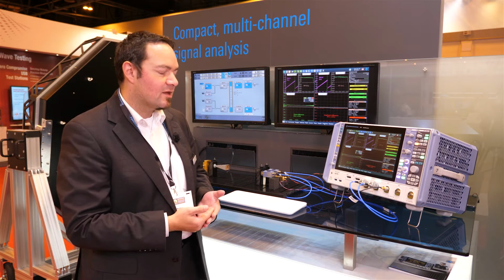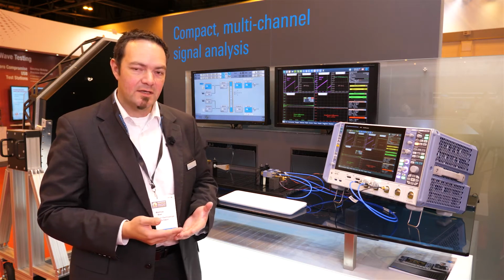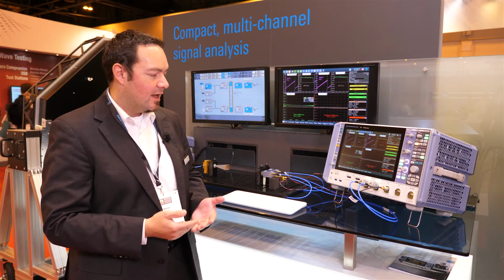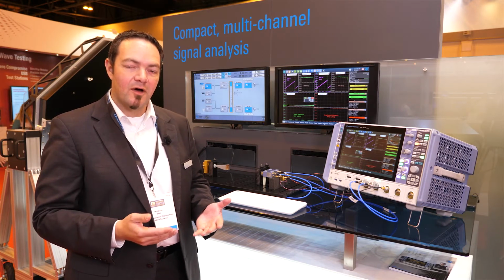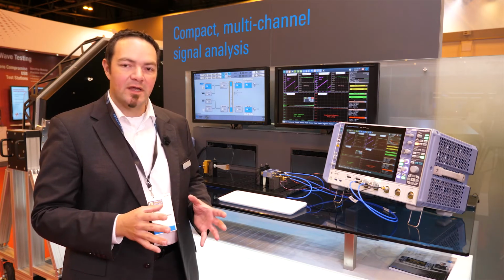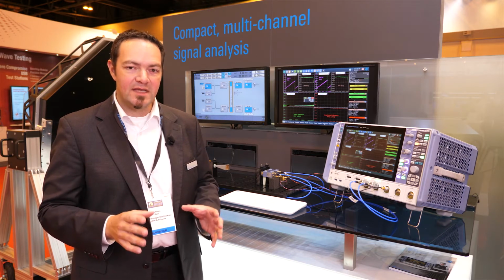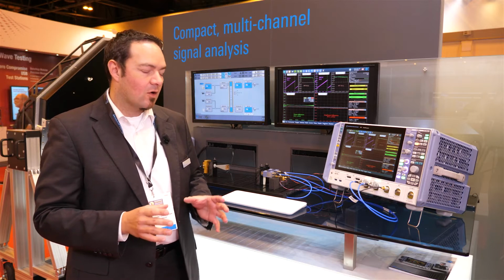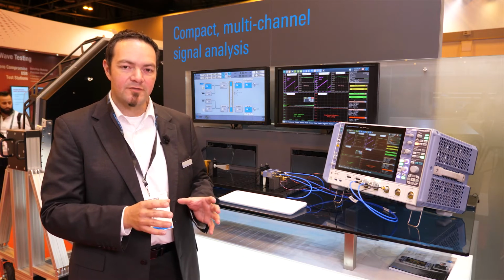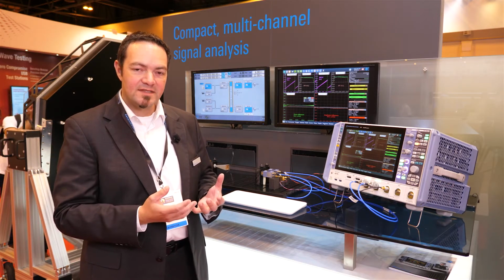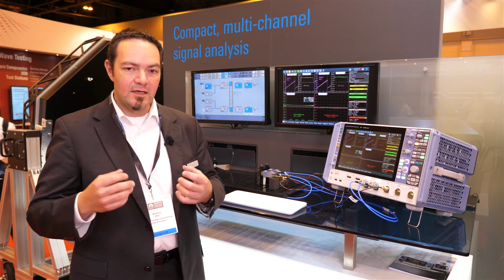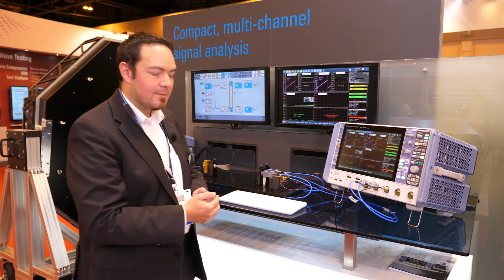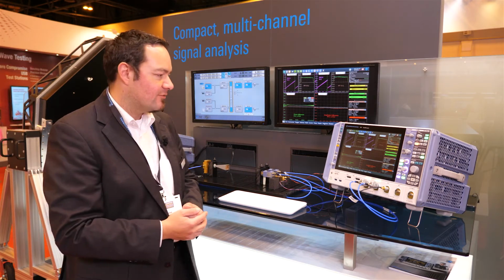We can do this because we have a very high acquisition rate with our RTP, up to 1 million waveforms per second. In addition, we have a lot of hardware acceleration, and last but not least, we have a real-time de-embedding capability. Real-time means in that regard that all samples coming out of the AD converter are compensated in terms of S parameters, which describe the signal path. And I would like to show you this briefly.